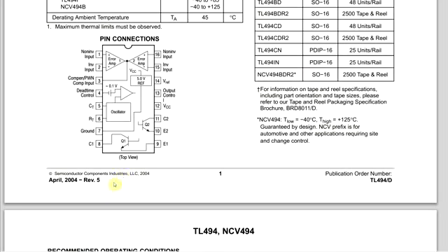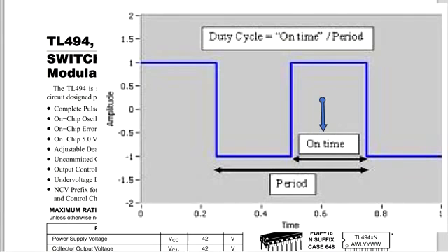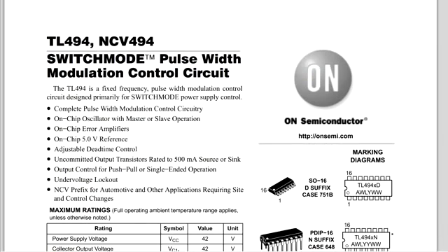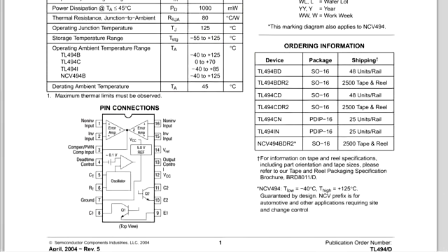TL494 is used in bipolar mode. You see the connections in here, and those connections I explained in part number 1. TL494 uses the pulse mode with two outputs working in flip-flop mode, that would be bipolar. When one impulse is activated, that output is activated, the other output is silent, and vice versa.